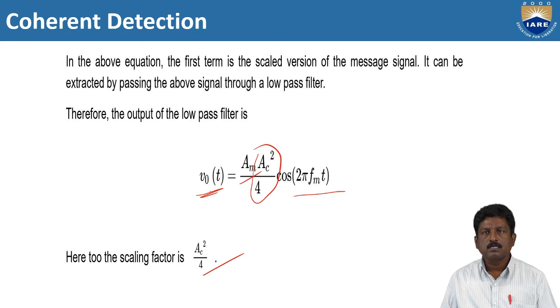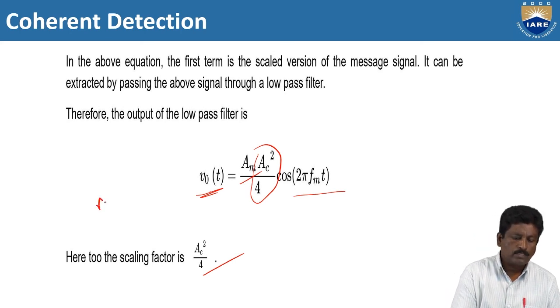So modulation here is the conversion of the low frequency component into high frequency. Because it is a combination of the modulating signal frequency FM and carrier frequency FC, both will be transmitted in the high frequency range. Coming to the receiver side, the demodulation operation takes place. So by the demodulation, you can filter the high frequency component and allow only the low frequency components. So you can observe all the demodulation techniques. Finally, our aim is to retrieve the M of T signal only.